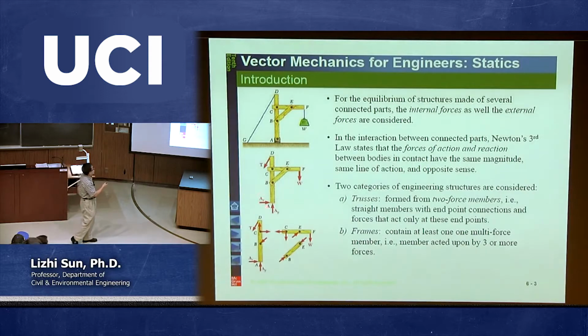And very easily we can calculate those forces, because for this typical two-dimensional problem, we have three equations, right? By collecting all the forces in x direction, that's the first equation. By collecting all the forces in y direction, that's equal to 0. That's the second equation. And then we can take a moment equation. For example, we're going to take a moment of all forces about this point, and then set equal to 0. That's the third equation. So we can basically solve these three unknowns, AX, AY, and T. So those are something we just talked about in chapter 4.